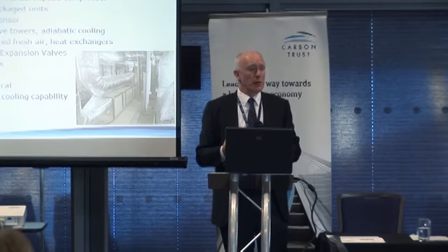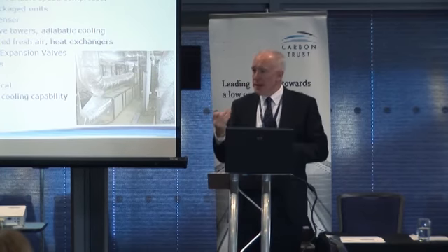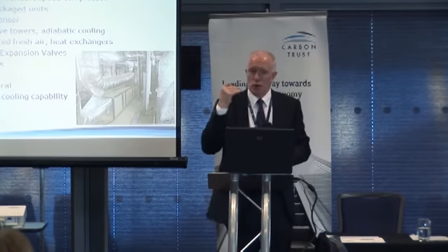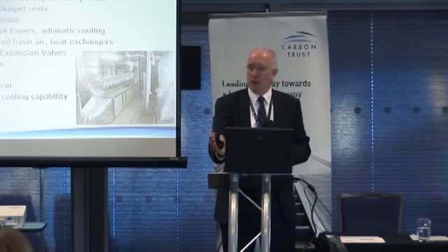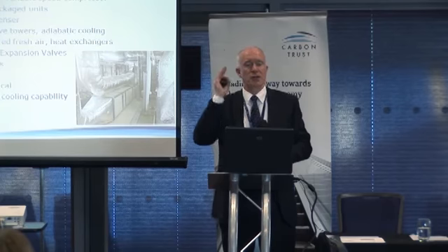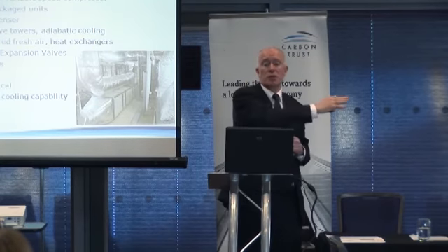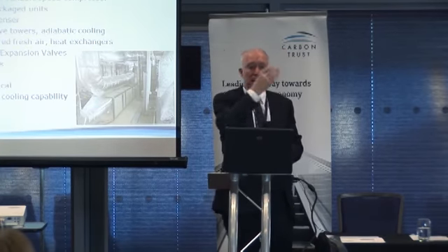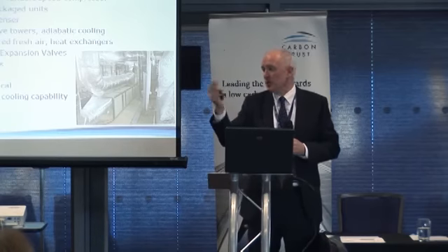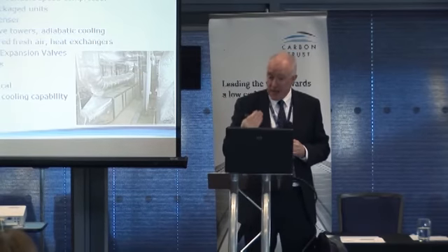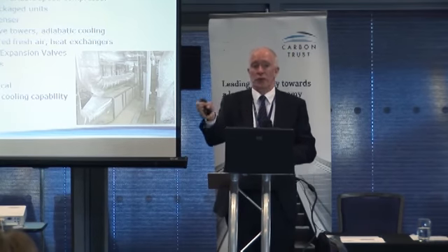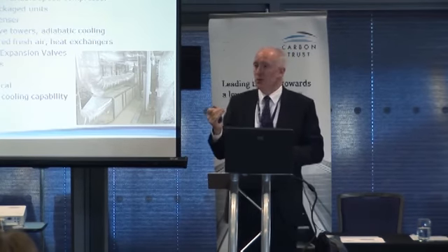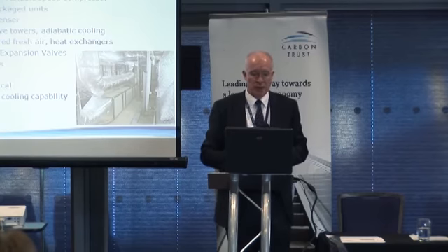People are using free cooling. The problem with free cooling is you may have some problems with humidity, so people are directly bringing fresh air through their computer rooms and to the cold aisle from outside, and taking the hot air and using it to heat their buildings. That is being used. They may need to filter it, obviously, if you're in a city environment, but that is being used very, very effectively. People are doing it indirectly as well, free cooling through heat exchangers if you've got a problem with pollution from outside, so lots of ways it can be done.